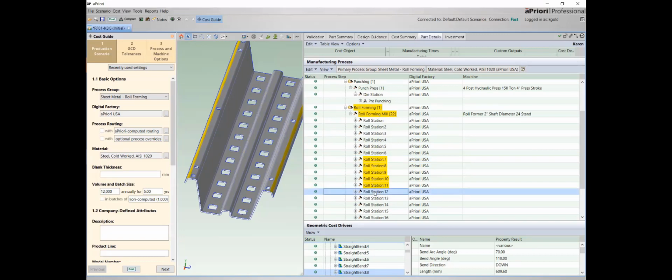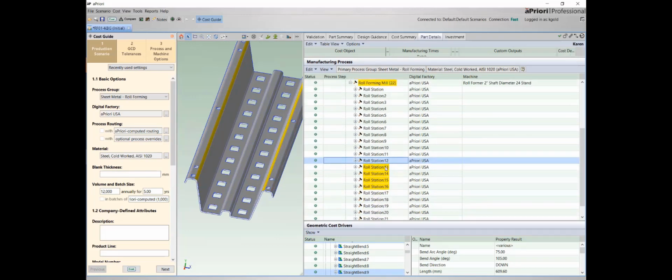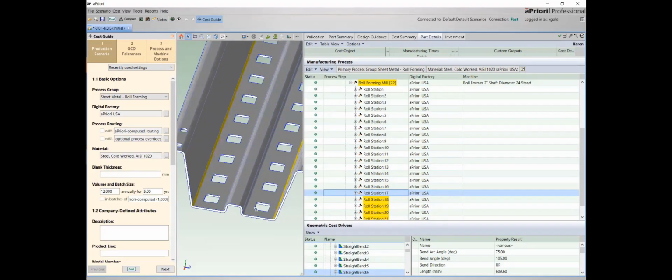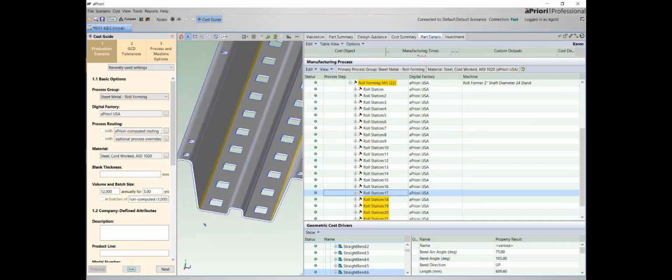If we move on to the next set of roll stations, then you next see that we're moving inward. This next pair of bends is made and also requires 5 roll stations to make it. And finally, these 2 inner bends are made, essentially folding the wings of this part upward into this almost W kind of shape. So other than the rib feature that we started with, we are working in an outside inward order. And that's done so that the bends are easily accessible and we minimize the size and complexity of the roll set tooling that would be required.